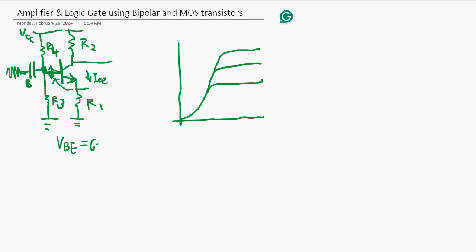It's about 600 millivolt. So this one is called an emitter follower, meaning the emitter voltage follows the base, because this signal is like a couple of millivolt. So the 600 millivolt doesn't change, because IE will not change that much. What changes is this voltage.